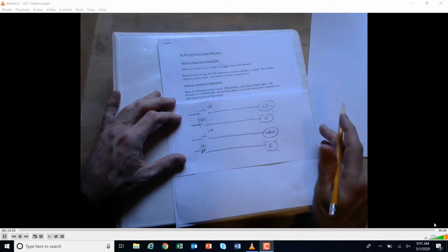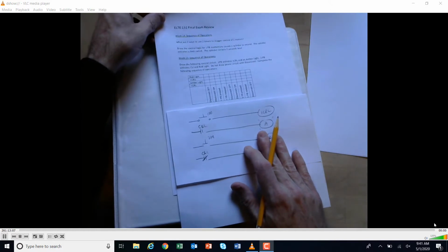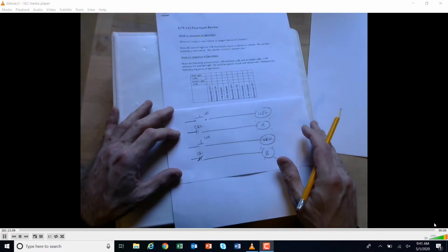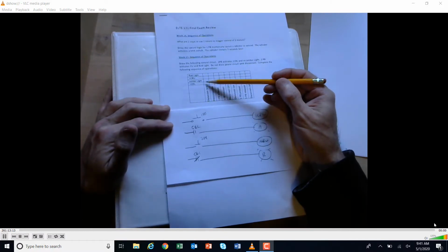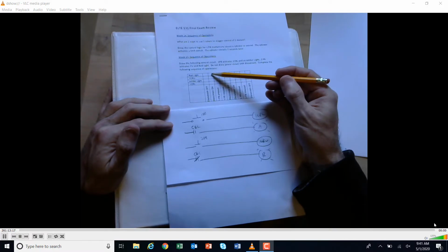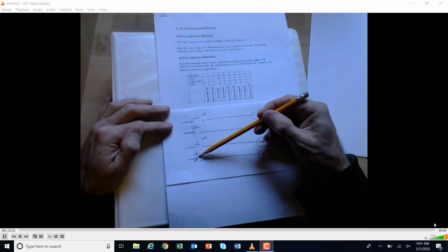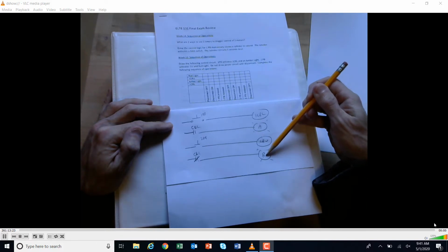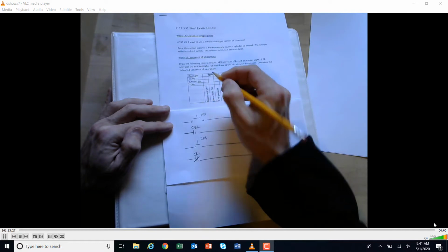Okay? And then if we're using this diagram right here, we want the sequence of operations that we went through. So let's say we had the disconnect off. Well, we assume nothing would be happening. Disconnect on. Well, we haven't pushed anything, but at that point we have this contact closed, so we would probably have the red light on.